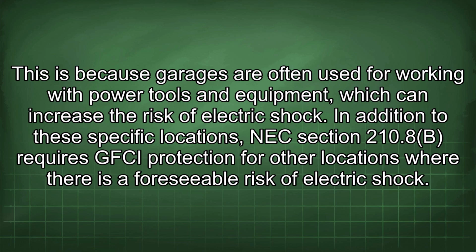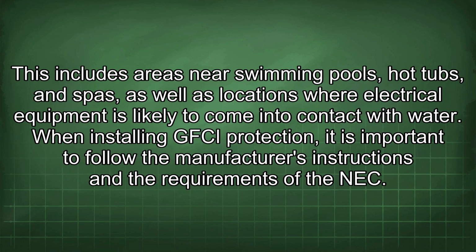In addition to these specific locations, NEC Section 210.8(B) requires GFCI protection for other locations where there is a foreseeable risk of electric shock. This includes areas near swimming pools, hot tubs, and spas, as well as locations where electrical equipment is likely to come into contact with water.